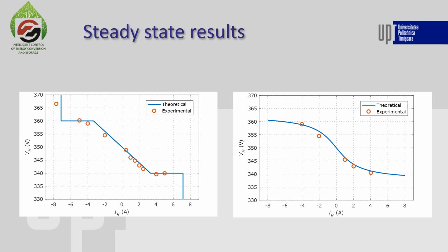These limitations are calculated based on the fixed limits for IL1 current and the maximum power limitation. With this condition, the maximum current values are variable within a small range when the voltages at the two inputs are drastically changed, as the duty ratio is also changed, and so is the ratio between the two currents. The limits are to be considered as a safety feature for protecting the converter, and the IL1 current is chosen because it is the larger of the two currents.